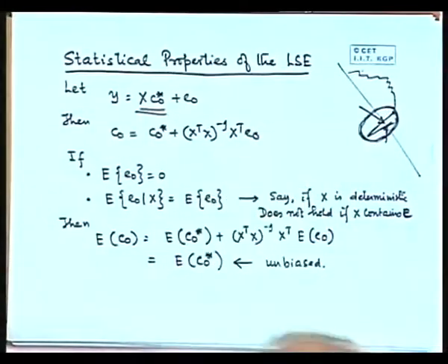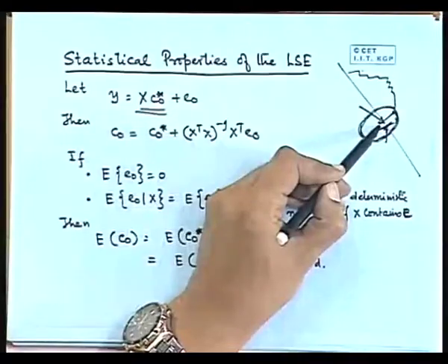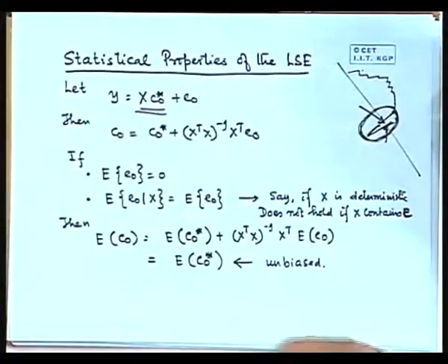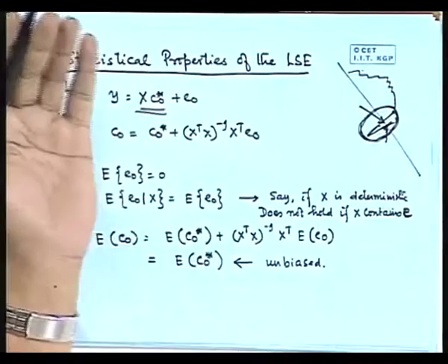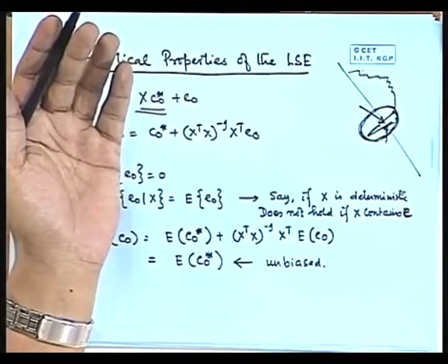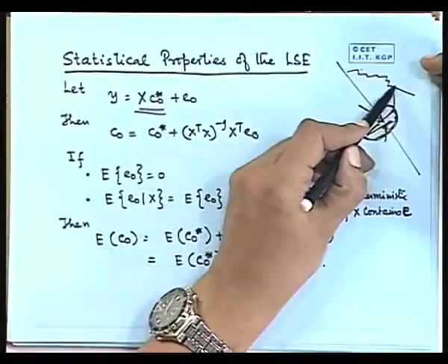So what is going to be the load? They need to anticipate it given the weather conditions, and so on. Because my net learned this behavior, every time during that part of the year, even if you take another year and give another load, on that day it will give this kink, because it has learned to give that kink. So it is very accurate on the set of data on which it was designed, but it is too accurate and it has lost its generalization capability.